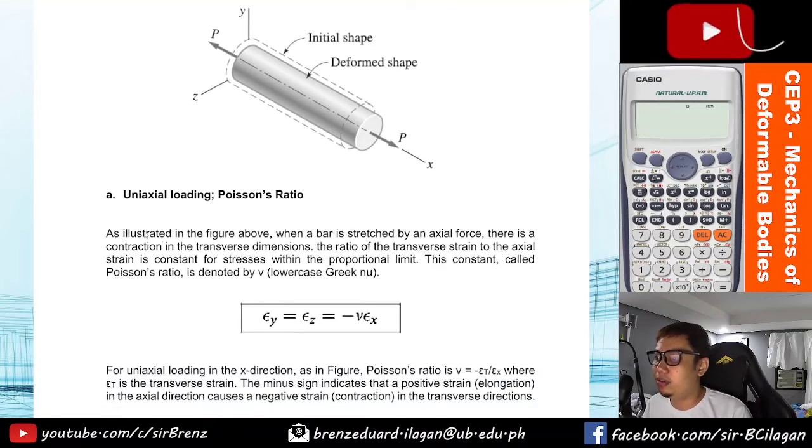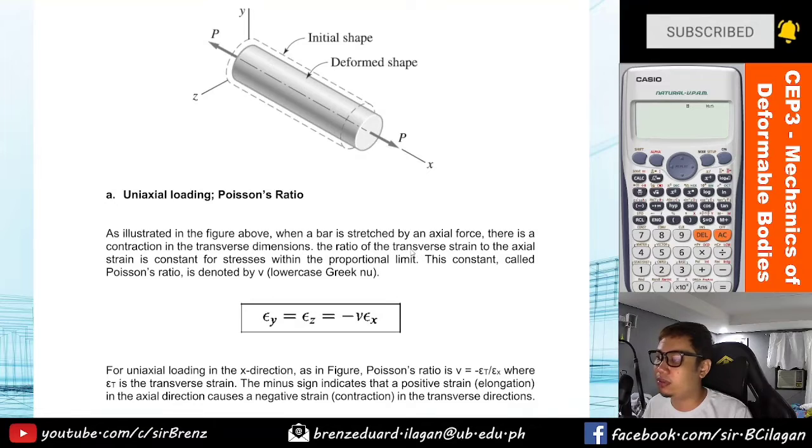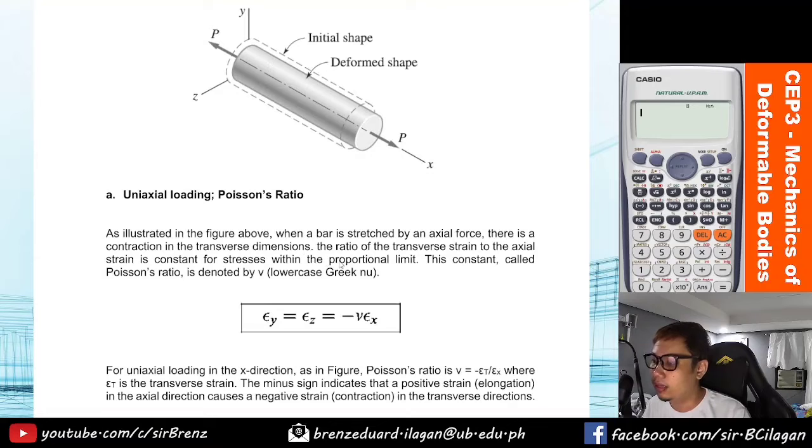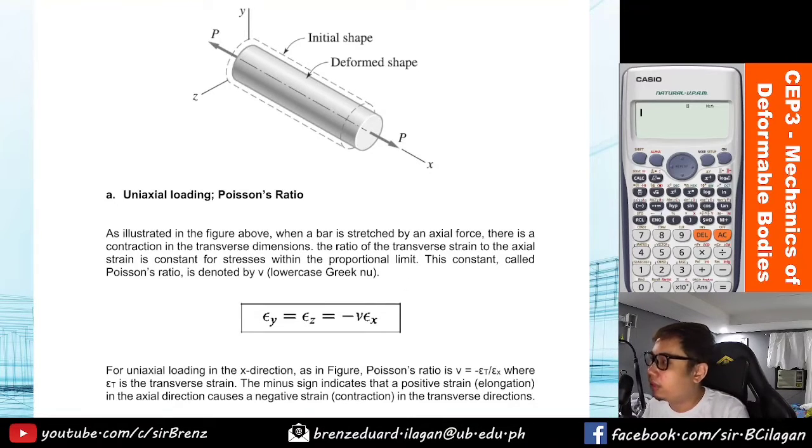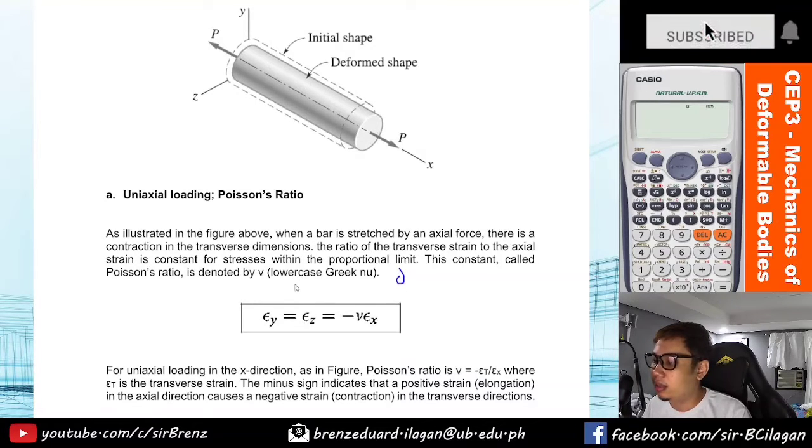So, under A, uniaxial loading, or our Poisson's ratio, as illustrated in the figure above, when a bar is stretched by an axial force, there is a contraction in the transverse dimension. The ratio of the transverse strain to the axial strain is constant. For stresses within the proportional limit, this constant is called the Poisson's ratio, denoted by v. But in other books, the symbol is also like a v, which is called nu.